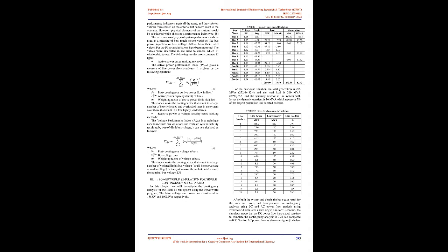These LSFs represent the expected change in the transmission line flows due to a change in generation or network configuration. These variables can be obtained using many techniques, but they are mainly categorized into two categories. Generation shift factors, GSF. The generator shift factors explain how the active power flow on transmission line L changes when the power generation unit at bus I is disturbed, as shown in equation 1,